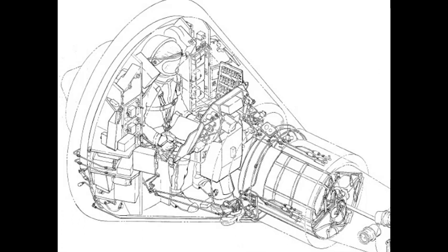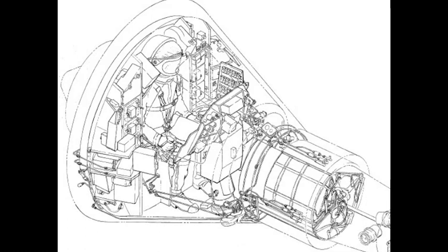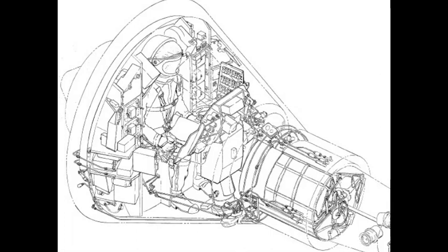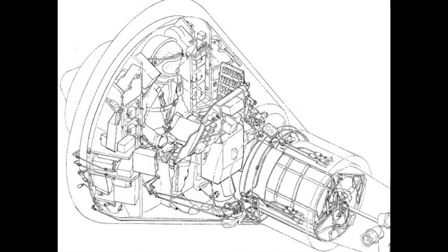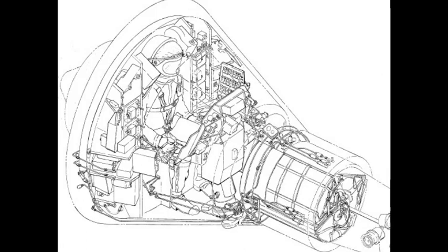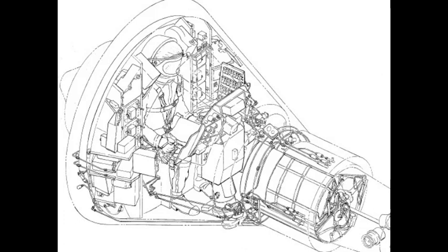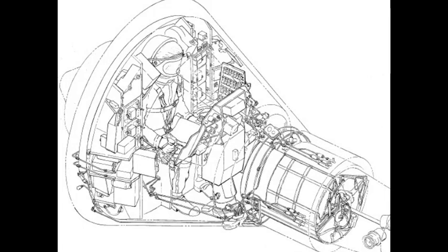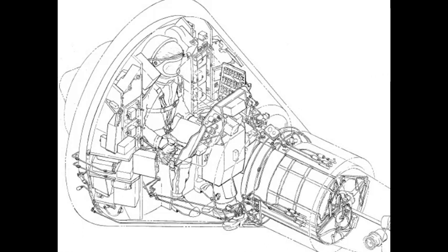A set of reaction control exhaust nozzles are internally located every 90 degrees between the compartment inner skin and the external shingle installation. The recovery system compartment interior is structurally divided into a left and right section. The compartment left section houses the recovery aids, electrical wiring, and plumbing routed through the compartment. The right section of the compartment houses a fiberglass container, structurally divided into 2 sections that contain the main and reserve parachutes. The container is removed by the astronaut from the cabin following capsule landing to permit egress.